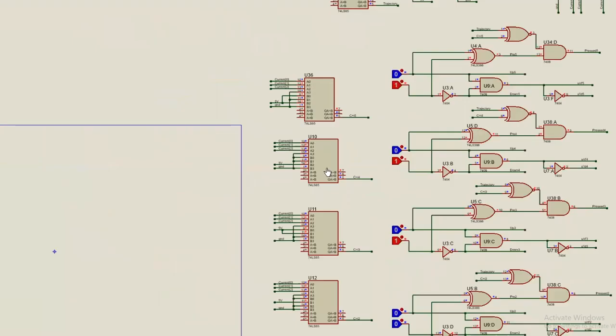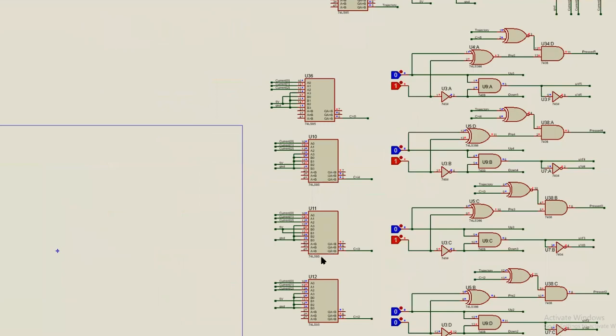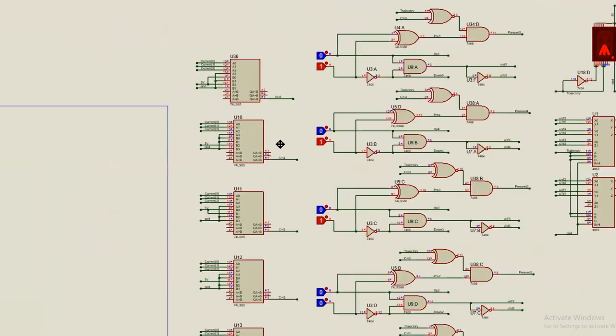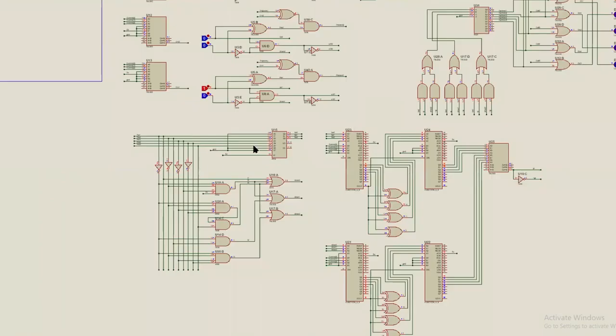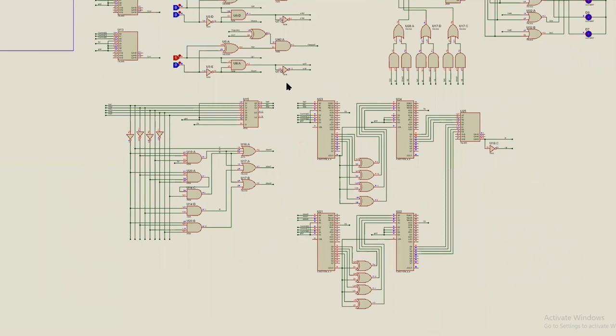As for the circuitry, we use comparators for comparing and producing the trajectory. We used priority encoders with 5 to 1 priority and 1 to 5 priority to produce the highest and lowest points, as we needed to calculate the furthest away points.